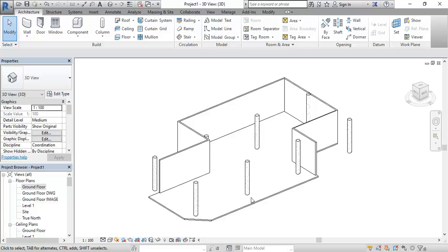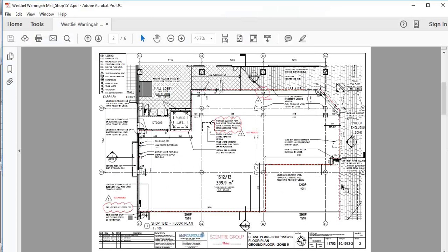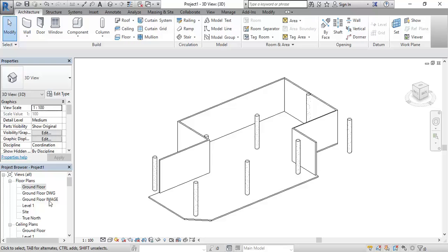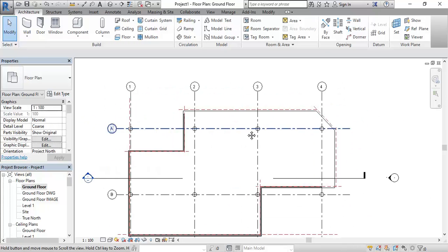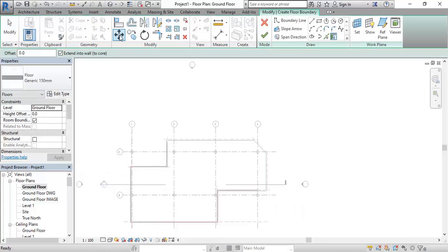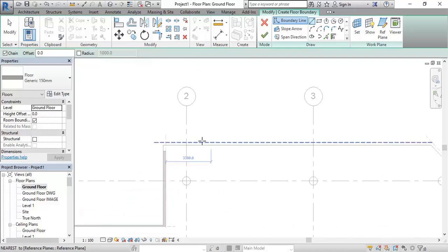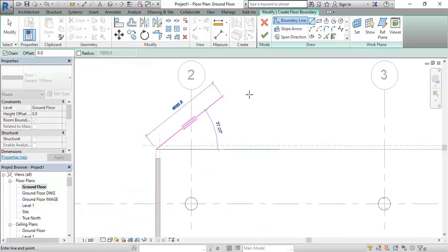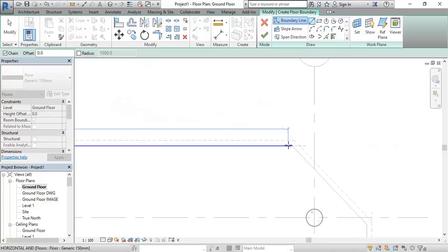If you want to finish it off a little bit more and have something with more of a base to show what's around the shop, then you could easily make another floor, and I'll do this really fast because it should be pretty easy. So I'm going to make a new floor, and now just with the line tool I can trace what I've just done just by clicking onto the edges of my previous floor.